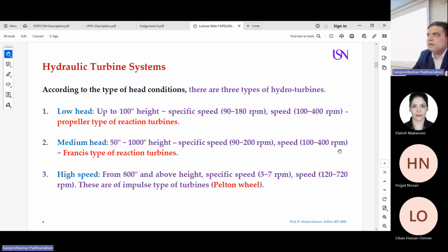Please note, in electrical machines, small machines, when the size is coming down, speed is very high. When the size of the machine becomes very large, for example, a hydropower plant, the turbine and the machine size is very big, more than this hall. If you go to the real power plant, the armature, the rotating part of your electrical machine, which is a synchronous machine, will be 2 times this hall. Then think the size is very big, am I right? As the size increases, weight increases, everything increases in the machine, am I right? So the speed comes down.